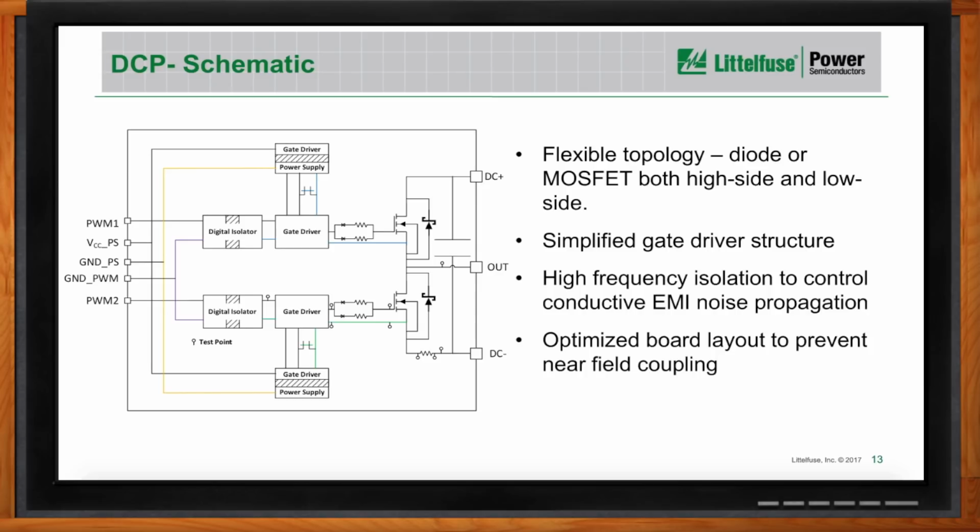It also has high frequency isolation. Both a digital isolator and high isolation power supplies allow us to control the conductive EMI noise propagation to avoid any coupling between the power stage and the control stage. It also has an optimized board layout to prevent any near-field coupling between the power stage and the control stage.